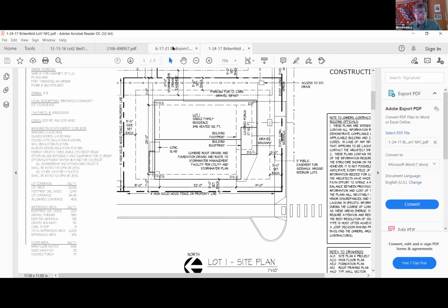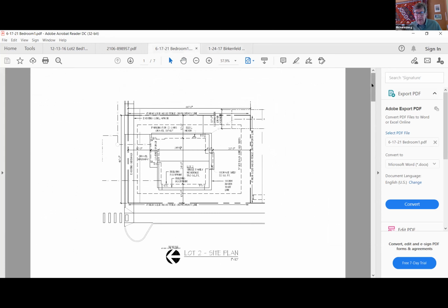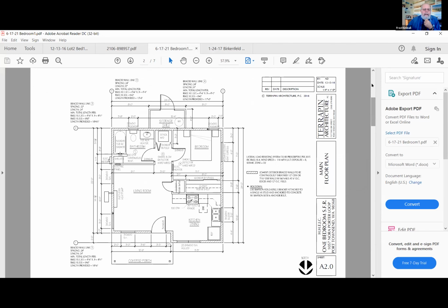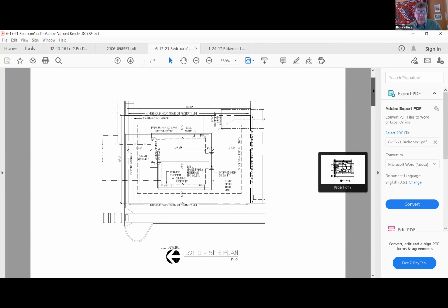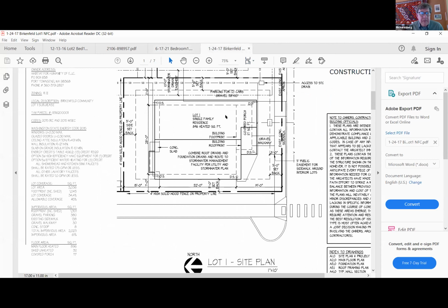I'm going to go on now to, maybe if you could point out some of the setback distances. Oh, that's a good point too. In the zoning code, there are a couple of different requirements. There's a maximum height, which in this case, since it's a one-story building, isn't really an issue, but if you're doing a 2- or 3-story building, it could be. Maximum height typically in Port Townsend is 30 feet, and there's a certain way that you measure that.